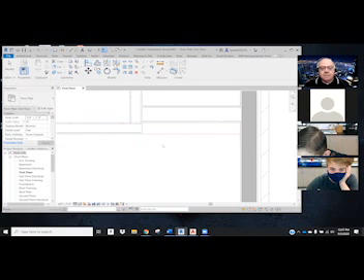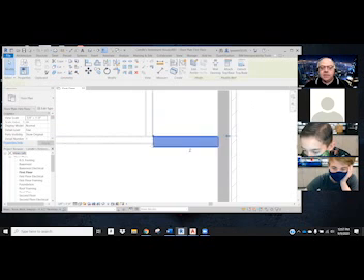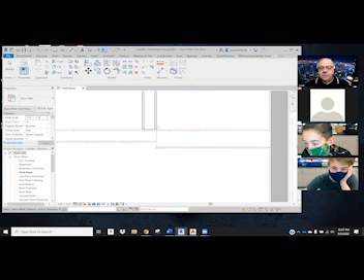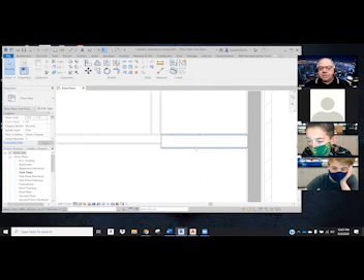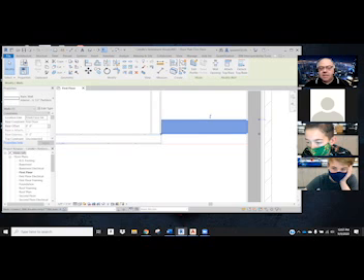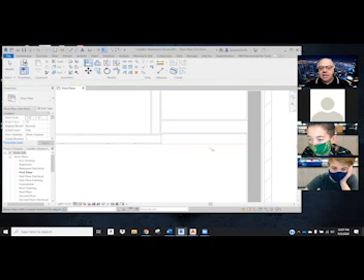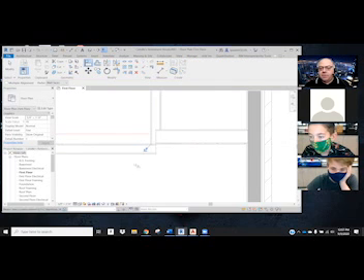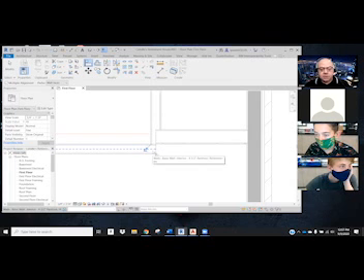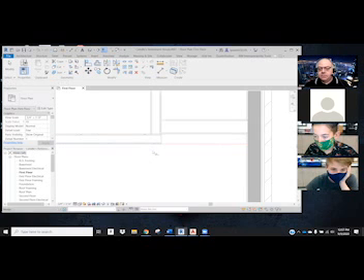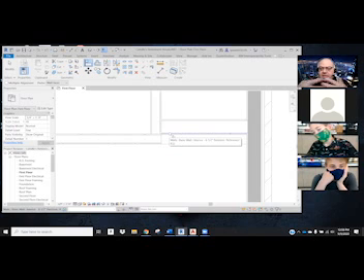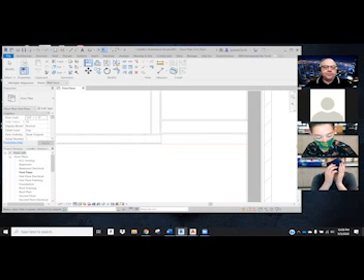Oh, that was bad. It joined there. So that wasn't good. I've got to break this up a little bit. Okay, so if they're still beside each other and that happens to you, when you flip a wall and you go to align it, and you do all the things you're supposed to do, and it moves the other wall, they're locked together, and they're not supposed to be. So I'm going to do a Control-Z to undo. And then what I'm going to do is I've got to break this union. It's kind of like they're meshed together.